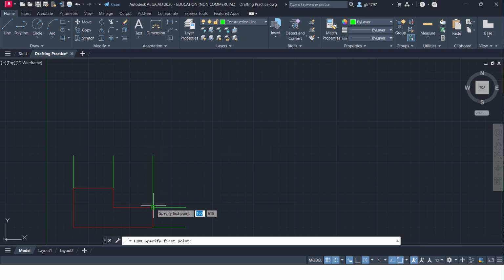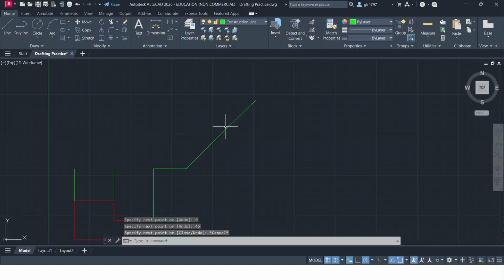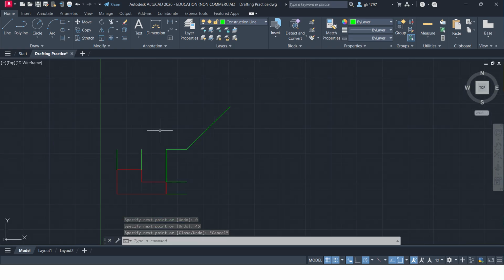So this line here at the right and upmost point, you're going to go 50 across. Make sure that is 0. Sometimes it says 0, but it's really a very, very small decimal. So we just need to make sure it is exactly 0. And then we're going to make a line that's roughly 150 millimeters wide on a 45-degree angle. And there you go. Now you have a reflection line. We're going to leave that alone for a minute.